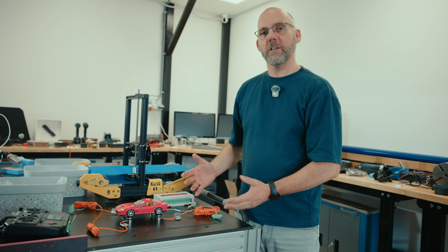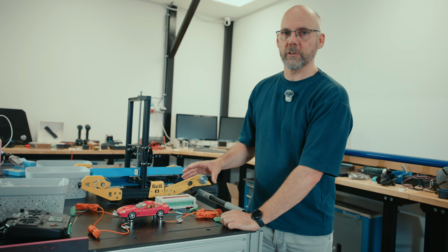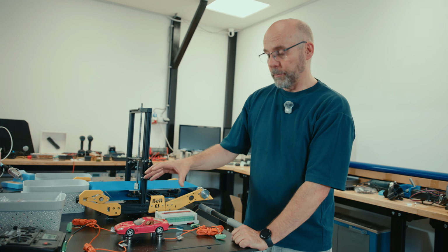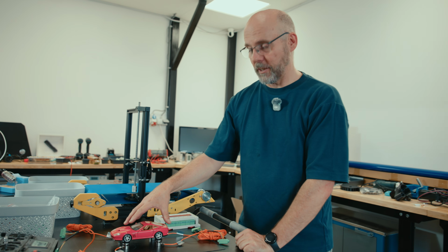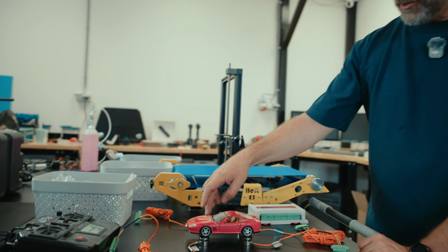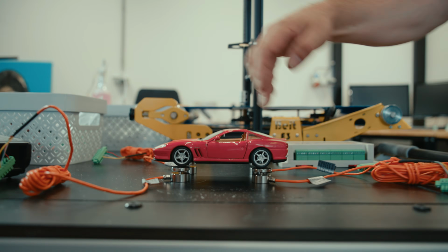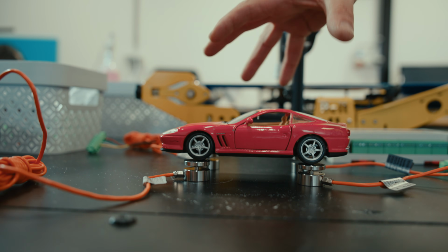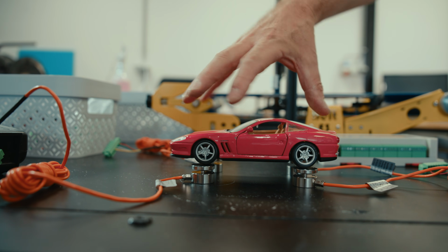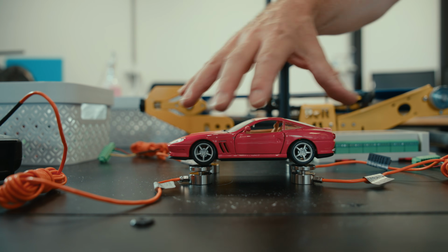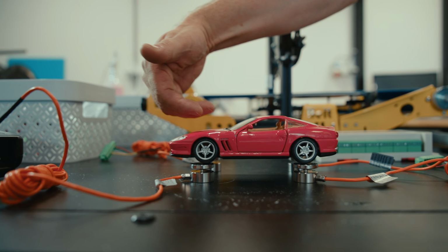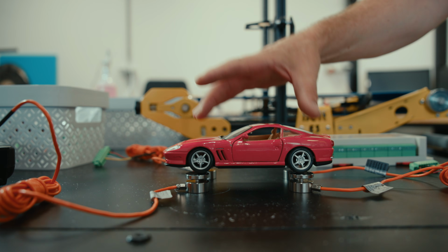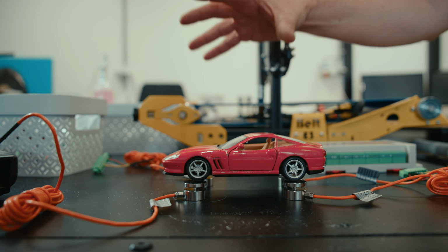In the floor of the test chamber of the wind tunnel, there'll be a lot of sensors. Obviously there'll be wind, airspeed, temperature, things like that. But we also have to measure the object that's in there. So we do that with weight sensors. So there will be a weight sensor on every corner. And all of that will be in a circular platform that can rotate. So we can rotate the car. So we measure with these 4 sensors. When the wind comes in from the front, we measure downforce. How much does it pressure left, right, front and rear on the wheels?